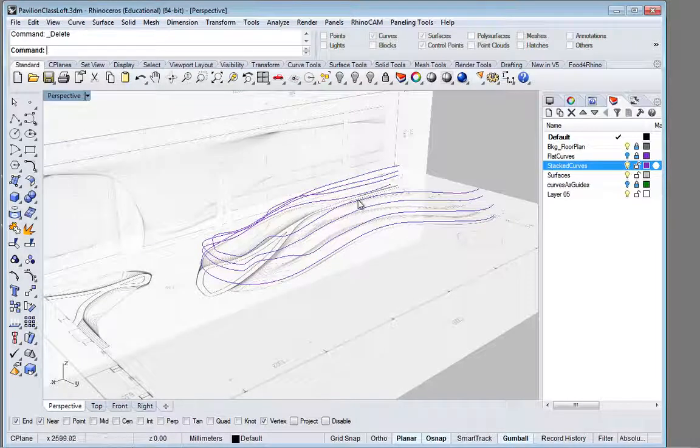When you're building a complicated shape like this, you're not probably going to be able to do a loft and get the whole thing done in one go, because there's a lot of ins and outs, and there's these plateaus. And what a loft does, you remember when we created this interpolated curve?